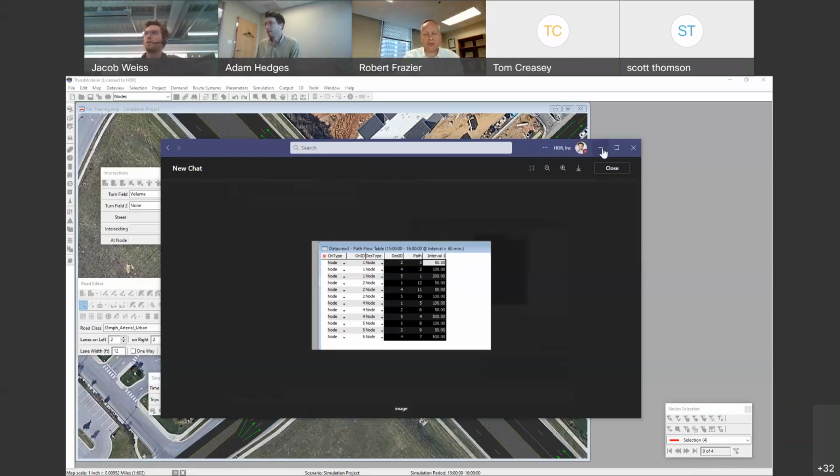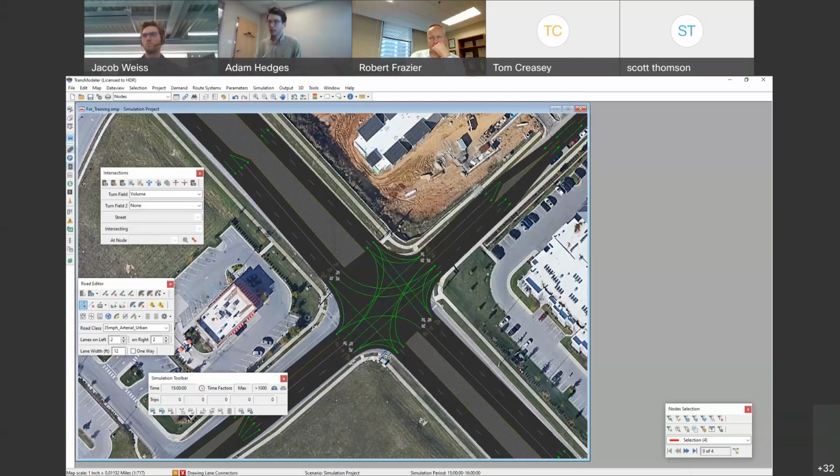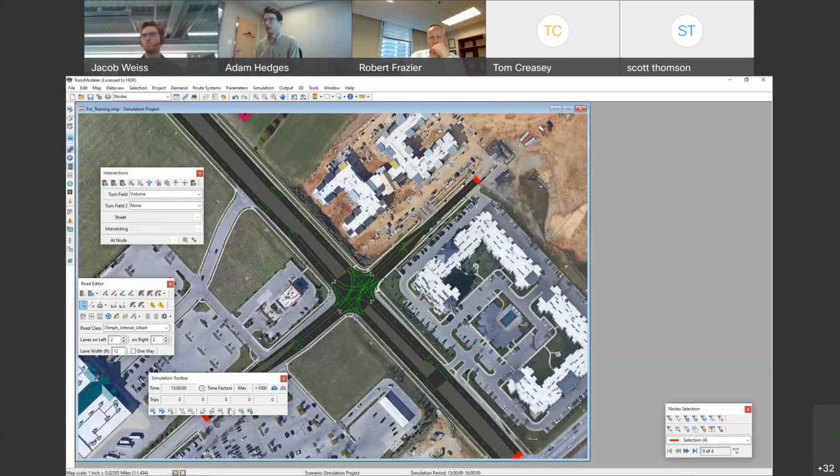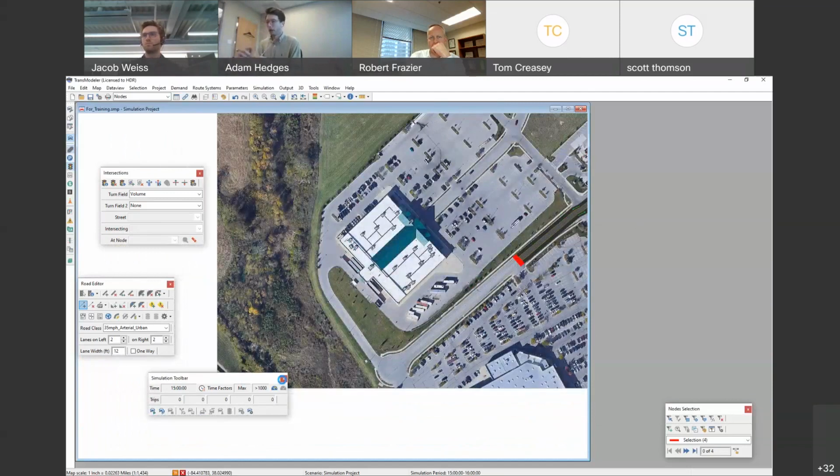So to wrap up the answer to the question, it's a little unclear if you can use both, but the recommendation would probably be to transition turning movement count data into an OD matrix when you can, and there are a couple of ways to do that. If you don't have streetlight or travel demand model data to create an ODME easily, you can start this way that Jake is mentioning, running the simulation through, getting these origin destination pairs, and then creating a matrix from that.